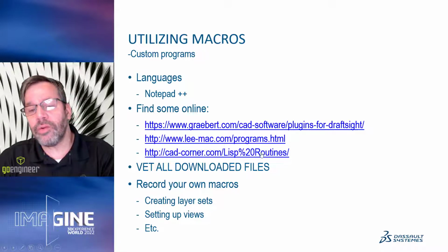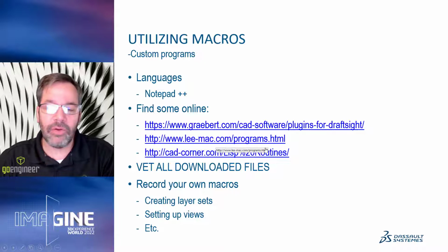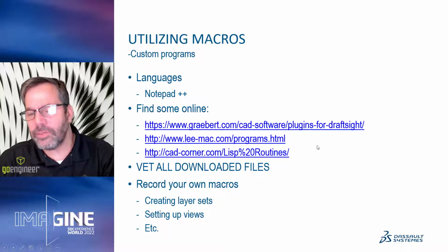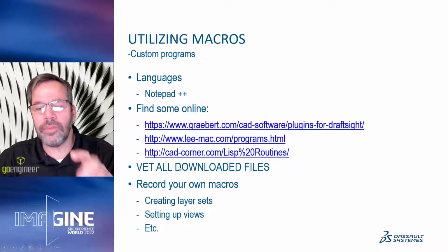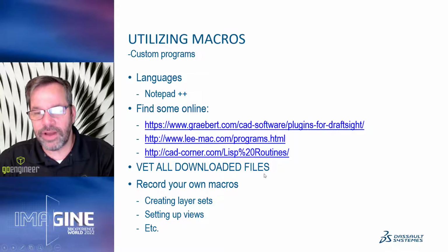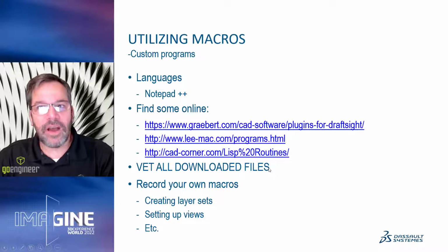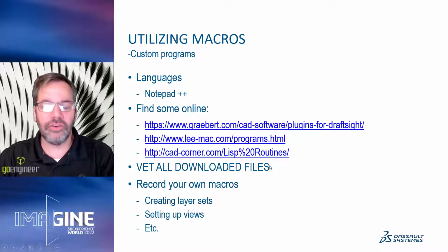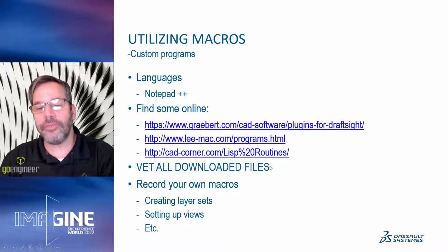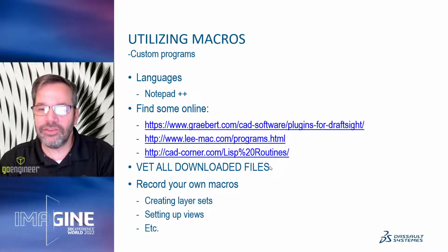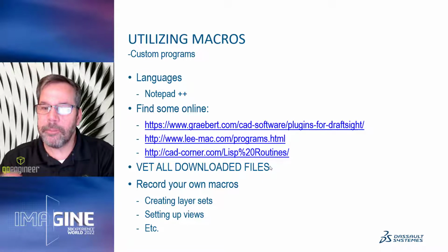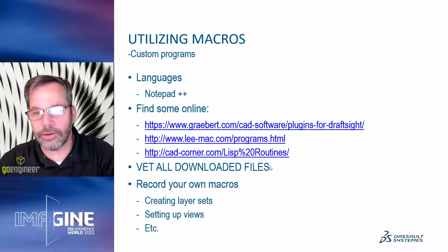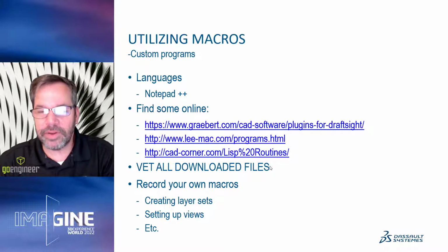I did run into a problem once where I downloaded a macro, not necessarily from one of these guys. And here I'm talking about vetting all downloaded files. This is where it came back and bit me. I have yet to find a website offering CAD macros that are out there trying to destroy your computer. But I had a macro that was creating geometry for me, and what I didn't pay attention to is the macro was putting it on a special layer. Now that layer doesn't conform to my company standards.